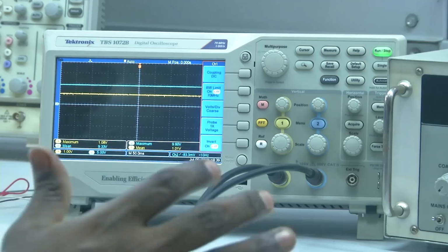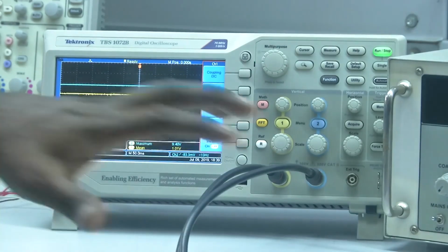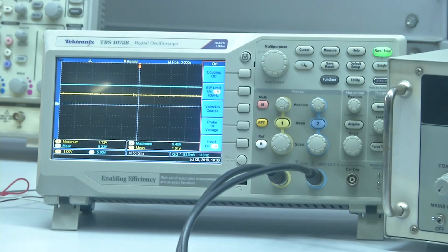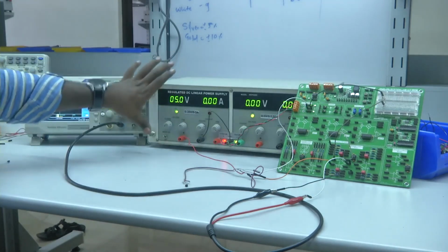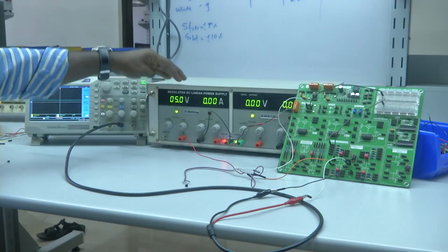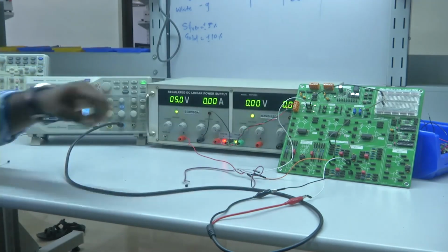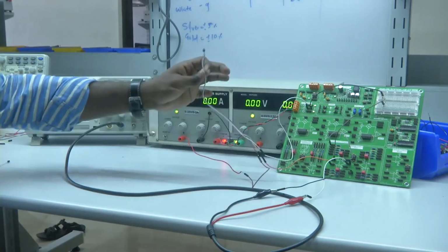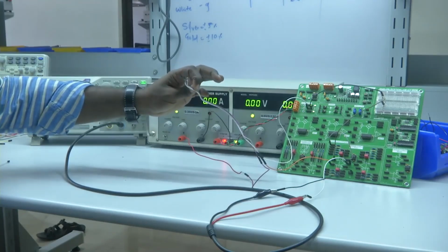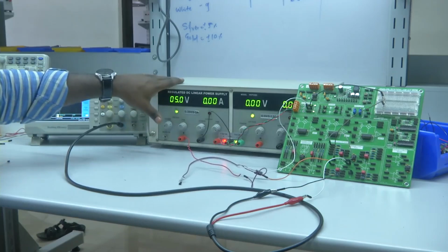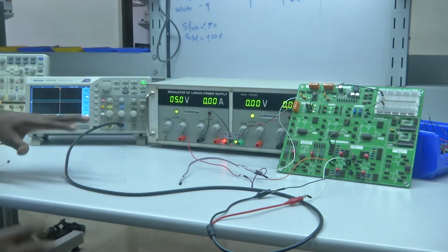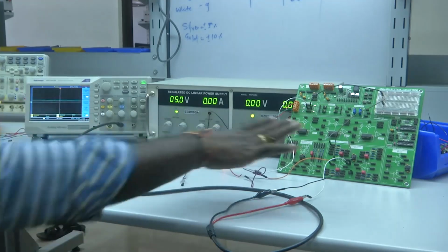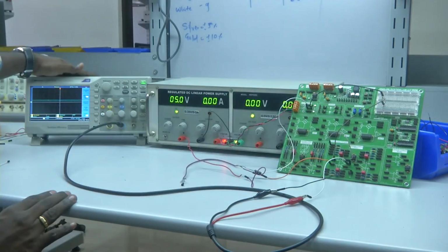Now, what we do is remove the connections on the input side and interface it to the LM35 temperature sensor. We will perform the same experiment as what we have seen previously. If you see the connections, I have replaced the input from the power supply with the output of the temperature sensor, connected to the non-inverting terminal. Since LM35 requires a supply voltage, 5 volts has been provided from the first channel of the power supply. In order to understand the actual temperature, the output from the complete stage has been connected to the second channel of the CRO.